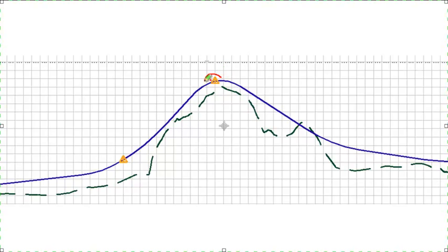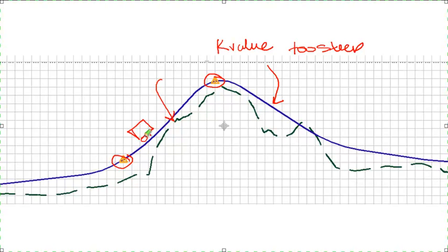Well, in this case, we're violating a K value. The incoming tangent and the outgoing tangent from our vertical curves have too great of a difference, too steep, which makes for a poor driving experience for a variety of reasons that you probably remember from your transportation textbook. Just unhappy cars.